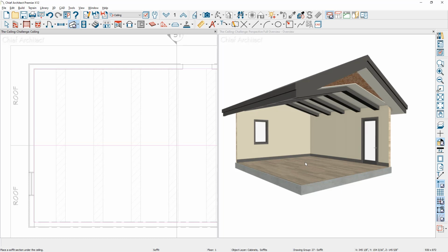You can create shelf rooms inside of the program. In this vaulted ceiling, we may have an entryway with a lowered closet or maybe a pantry inside of a vaulted kitchen. Let's take a look at creating a shelf ceiling room back in this corner. In the plan view, I'm going to use our interior wall tool, and I'm going to just come in here and create a simple rectangular room.